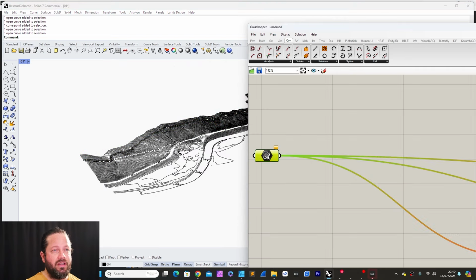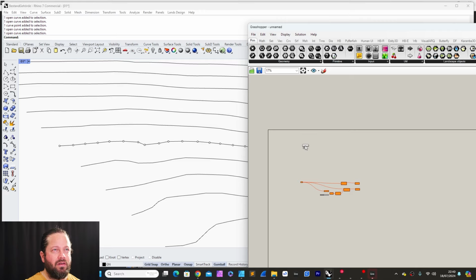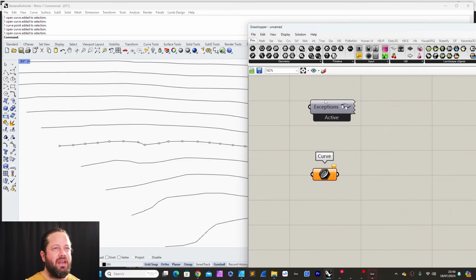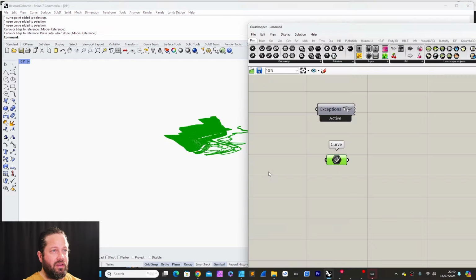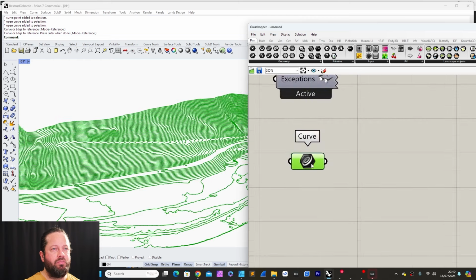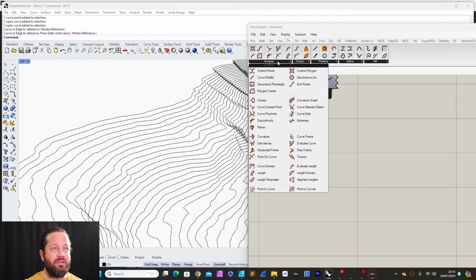So the first one is, if I have polylines, then first we bring in the curves. Grab this here. Set multiple curves. I'm going to grab everything, enter, and now they're all selected. Now the next step would be to extract the control points of these curves.